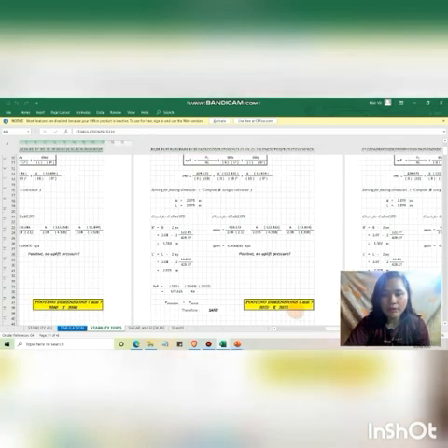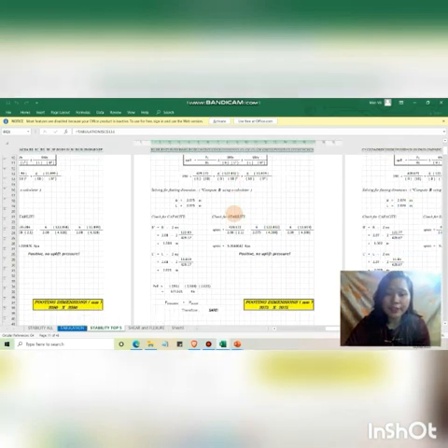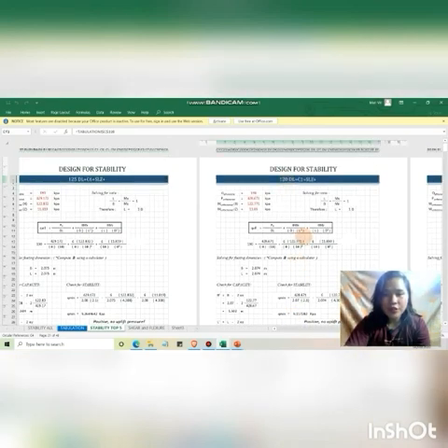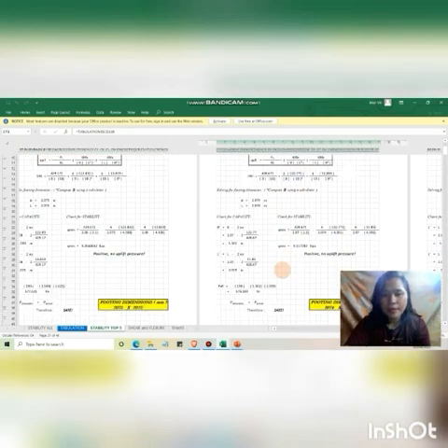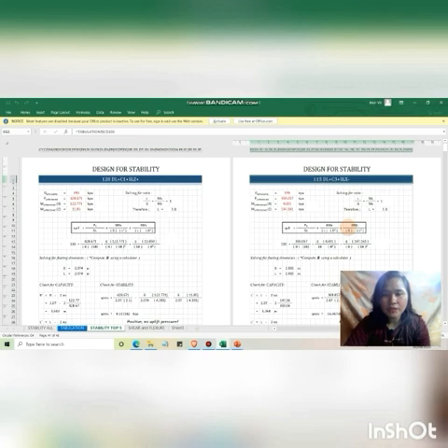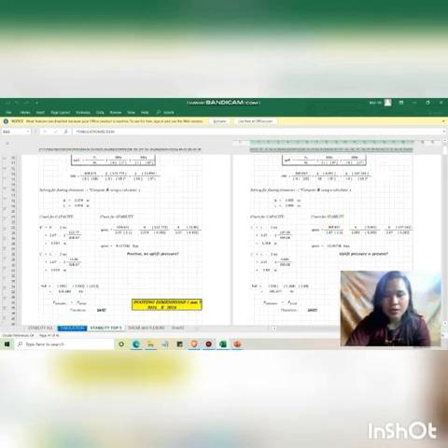For our top 3, load combination 125 with dimensions 2075 by 2075. For our fourth one, load combination 120 with 2074 by 2074. And lastly, for our top 5, load combination 115, resulting in a footing dimension of 2065 by 2065.